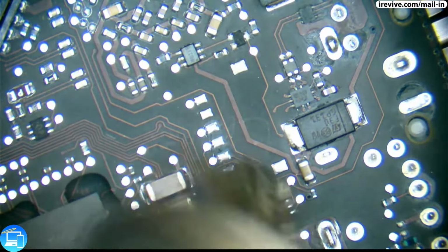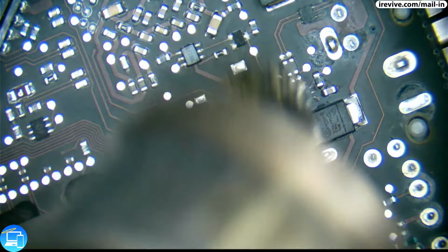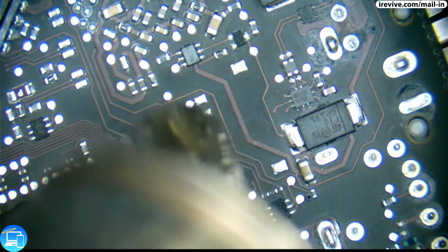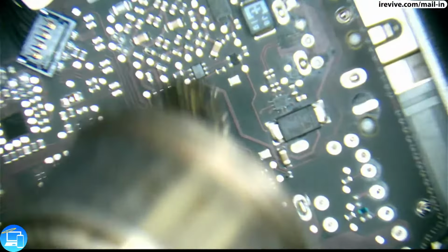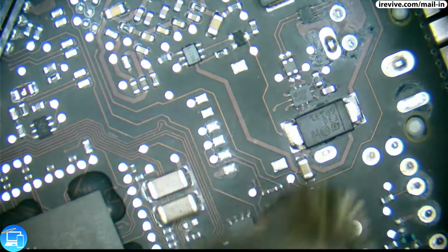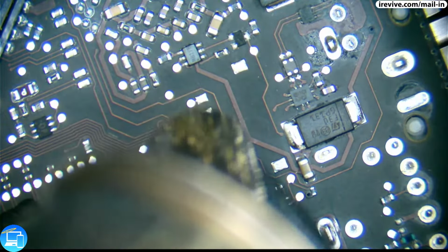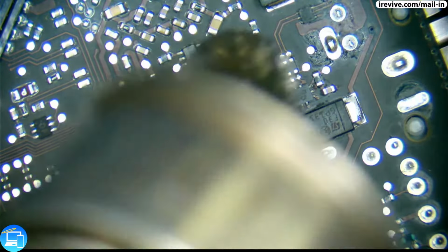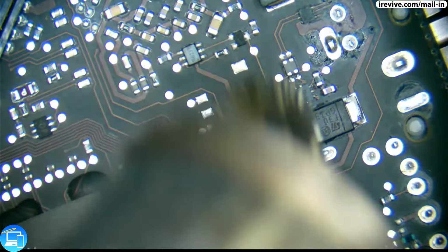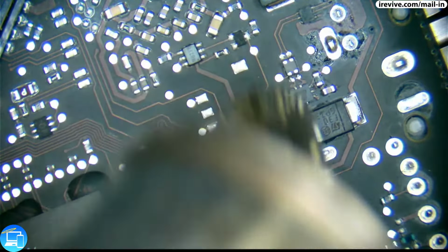And so I'm just using around 450 Celsius heat because I've left it in the case. I don't want it to get too hot to where it melts anything else in here, like the keyboard on the other side. And I'm really just trying to raise the ambient temperature of this logic board so that it's going to be that much easier for us to solder on our female terminal.